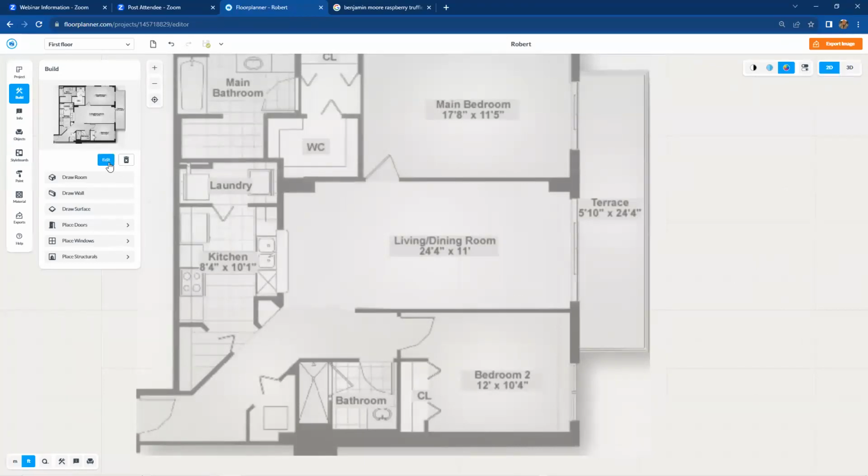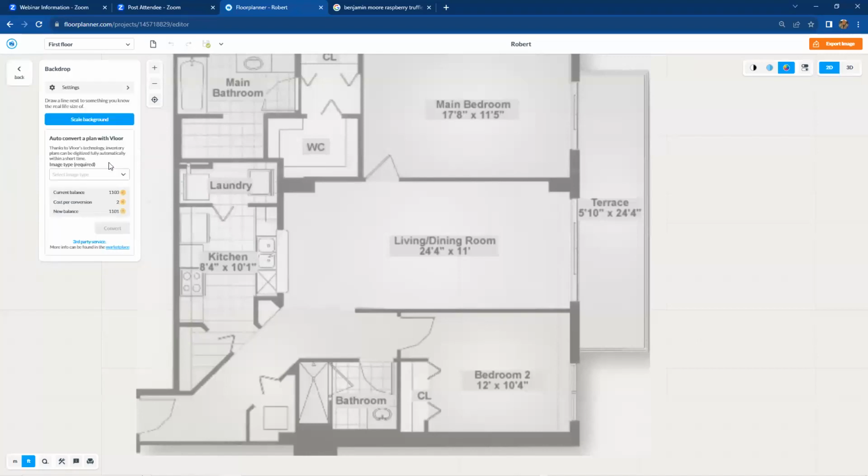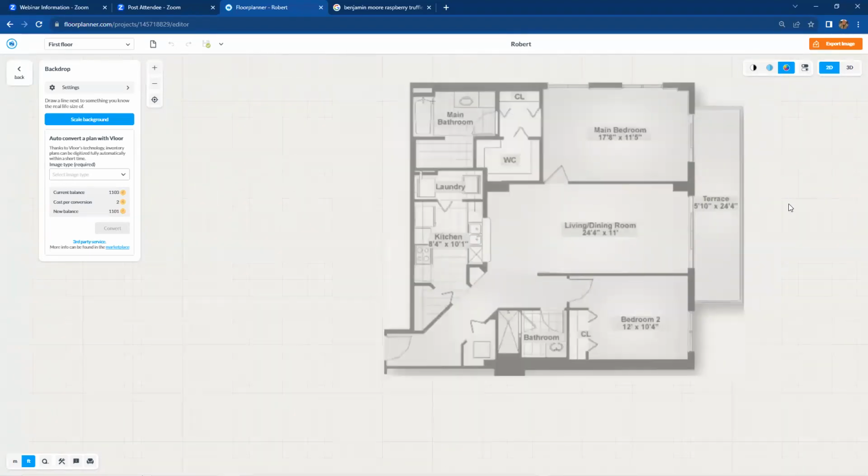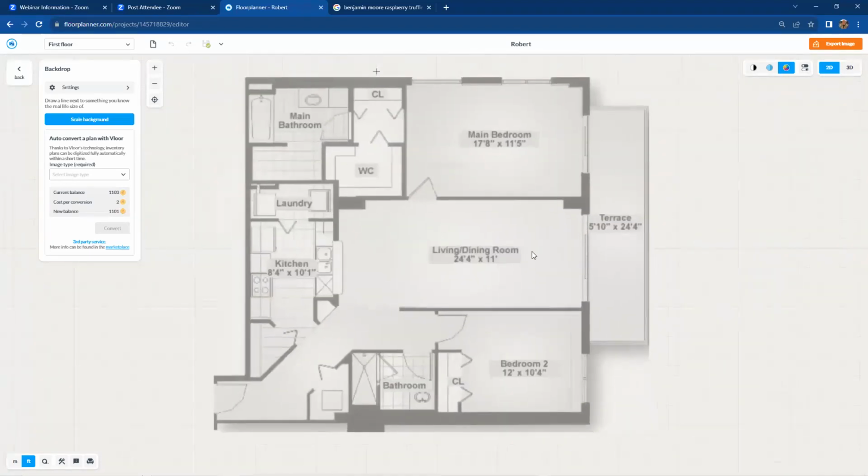So if I go to the Edit tab in the upper left-hand corner, Edit, and say scale the background, scale this background, draw on the canvas. What that means is it wants to know the 2 points. So I'm going to left-click with my cursor right on the drywall edge as 1 point, go across the way somewhat parallel to the other edge, left-click, second point. 1 point, 2 points, and what distance is it supposed to be? Type it in as 11 feet and hit enter. And there we go. This has made this floor plan real world scale, 1-to-1, 1 foot equals 1 foot.